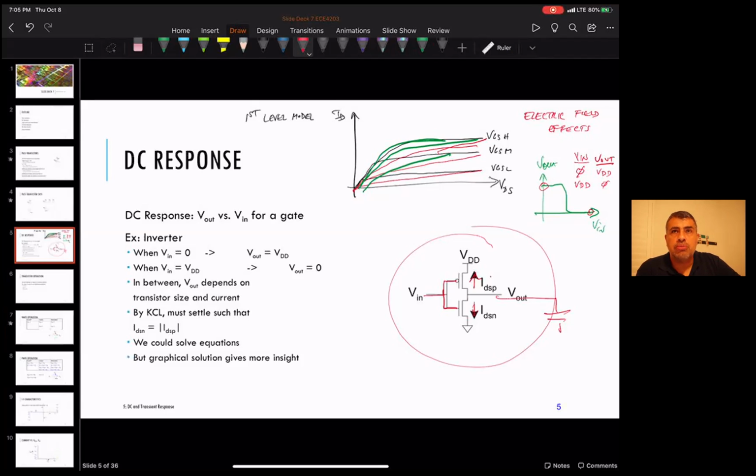You just take your oscilloscope probe, see if you can, I mean, I don't know if you can find the power supply, but if you put it on a power supply, you won't see a straight, flat 1.8 volt or 1.2 volts or whatever it is. You'll see this guy going crazy, fluctuating, depending on what the chip is doing. So that's the importance of this sort of a transfer function from a noise margin perspective. It's really, really important to have a lot of noise margin.